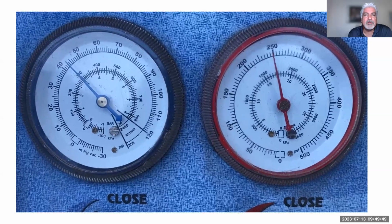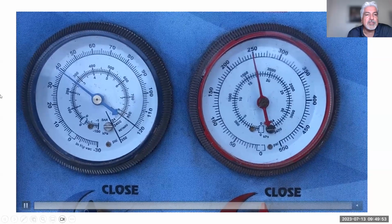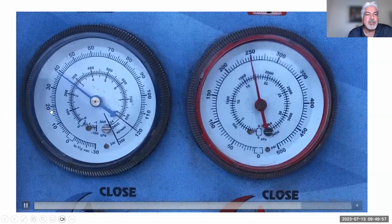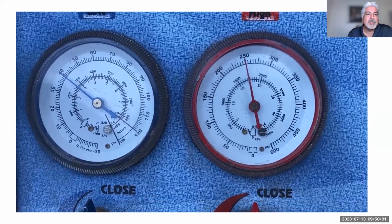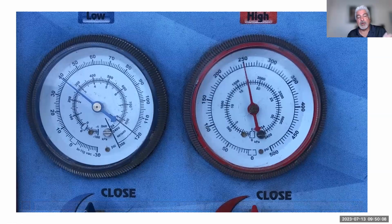So we see about 250 right there, and we're cooling down, cooling down. We're creating a suction. And in this case, you're going to see it cools down and it continues to drop. Okay, that's normal to see. As the engine ran further, it continued to drop. So that's a quick look at what the gauges are doing as soon as you turn the AC on.